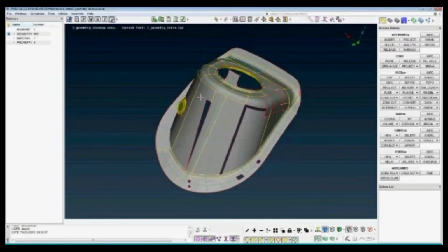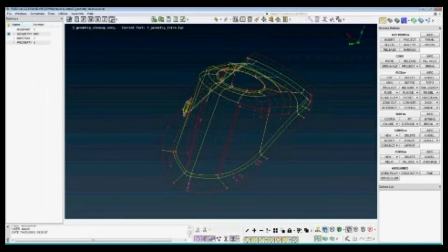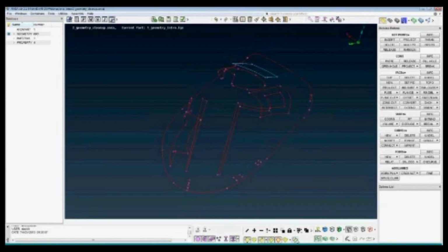So first, we're identifying more problematic areas. A good way is to deactivate the shadow, deactivate crosshatch, double, triple boundaries, and just see the single boundaries. These are free edges. Should it be this much free edges in the model? Or it's indicating that there are several problems in the geometry.